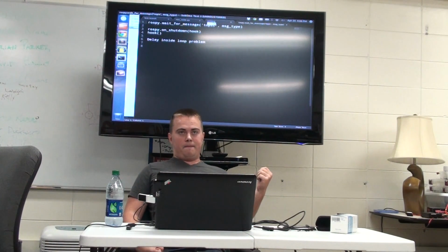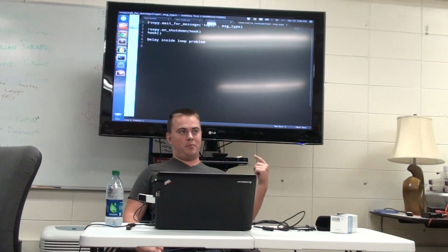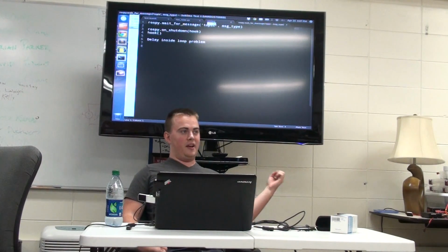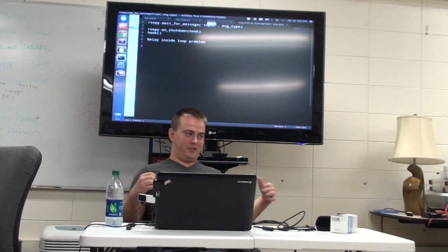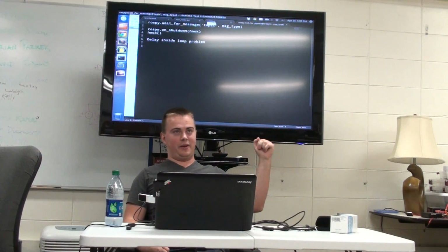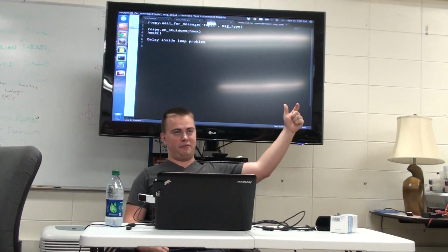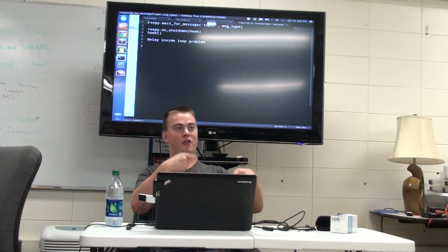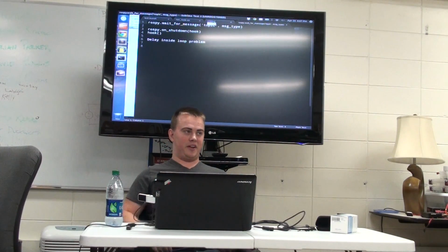The problem that can arise is if you have your callback and your while loop running, and the while loop starts running before you get your first data, then your initial value for the location is going to be 0, right? And then when you actually start, it's going to jump off to some other place, and that'll completely screw up your map. So the solution that's typically used is to have a flag in our callback, like received equals true, set on the first received message. Then at the beginning of our while loop we can say wait until received equals true, and then we'll actually do our code, so that doesn't happen.